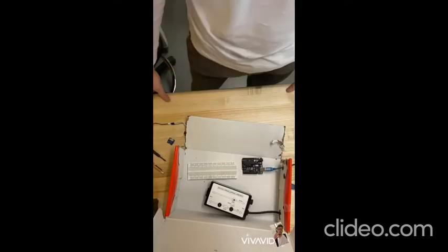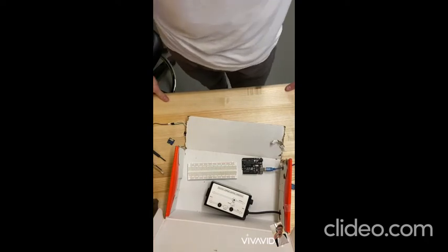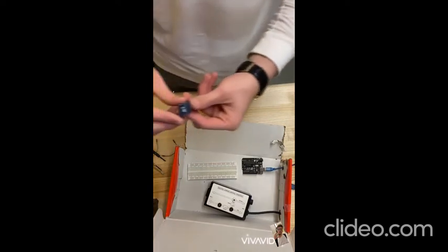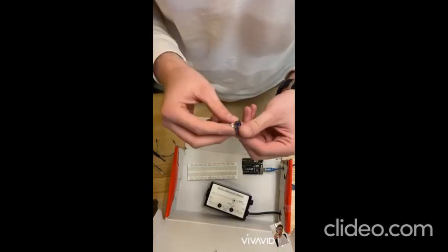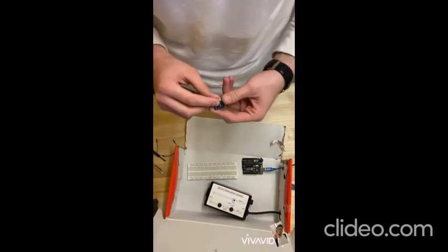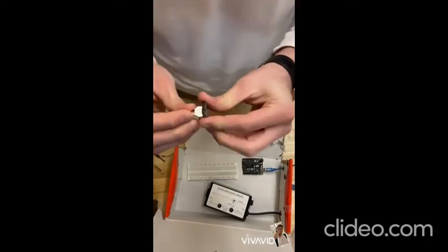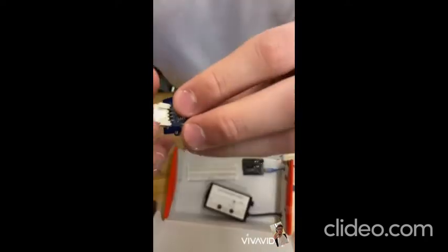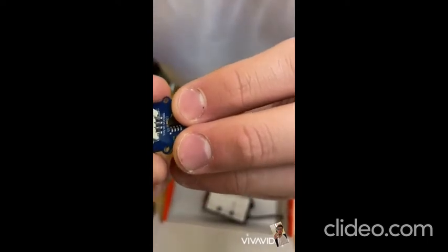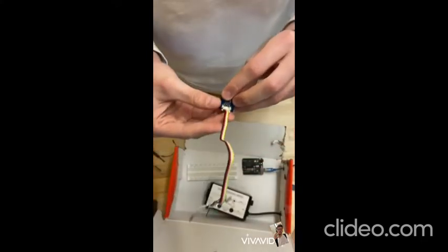For a better demonstration, I decided to rebuild the circuit live in this video and explain what each component does. So first of all, this is the temperature sensor, which is going to be connected to one of the analog inputs in the Arduino. You can see here there are 4 pins: the ground, VCC, NC, and signal. We're going to be using the 3 pins of signal, VCC, and ground for our project.